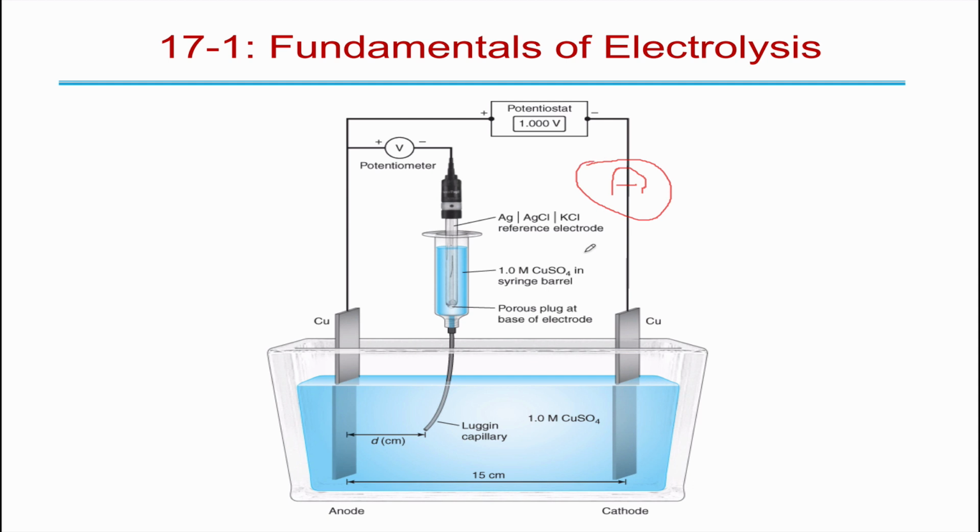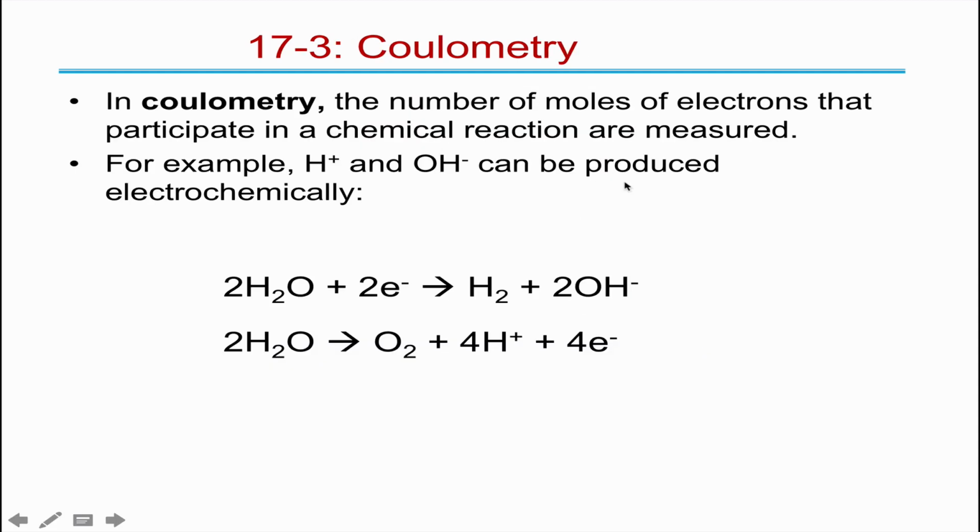And so this potentiostat is going to feed back into there. This voltage is going to feed into the potentiostat. It's going to adjust the potentiostat to get this electrode at the right potential. And then this ammeter is going to measure the current that flows in that circuit. A 3-electrode potentiostat. And we'll come back to this again in the next couple of lectures.